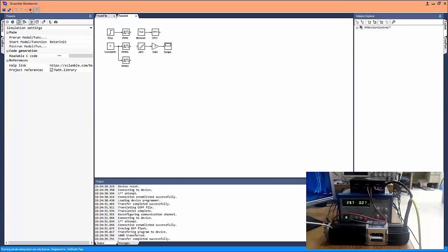In those scenarios, instead of using an incremental encoder, we would usually use an absolute encoder so that the initial position can be known even when the system is powered up after a complete power down. Alternatively, Hall effect sensors could be provided on the motor so that one of the three phases or a combination of two, which is closest to the rotor pole, is excited instead of exciting the A phase by default. This would ensure a minimum possible initial rotation for alignment.